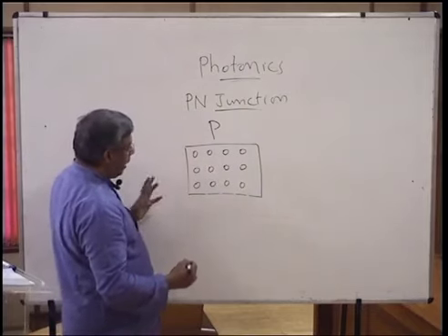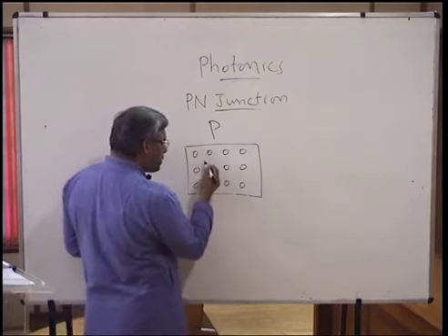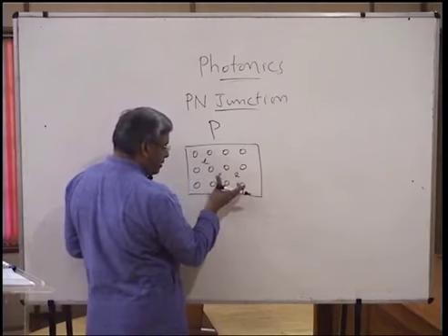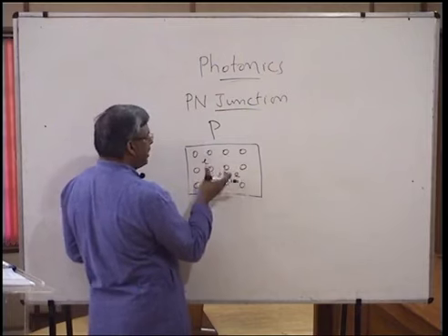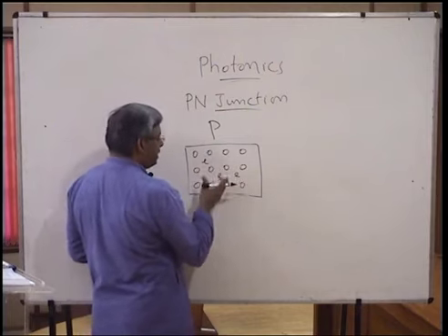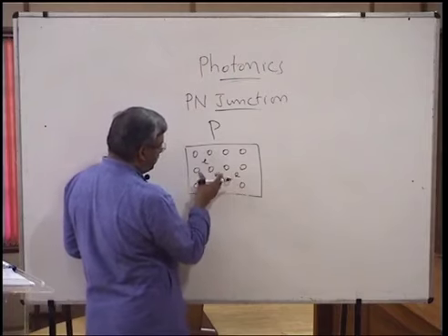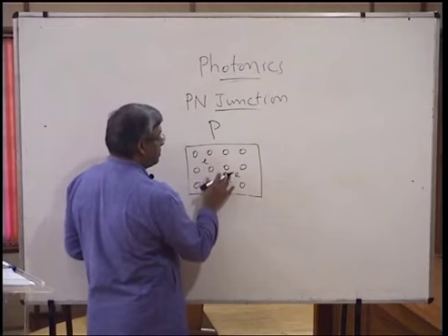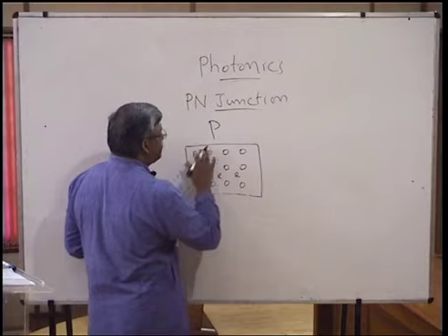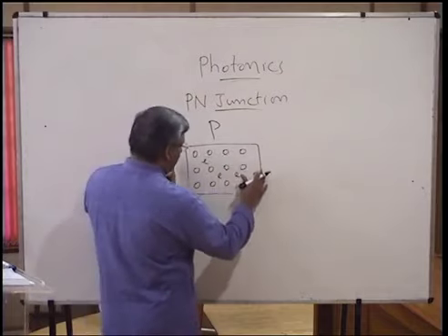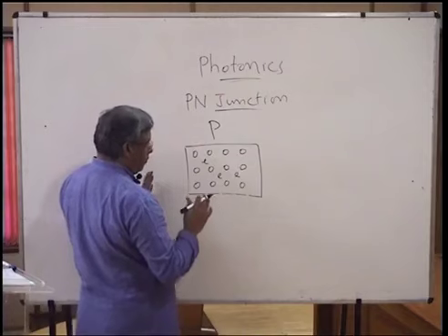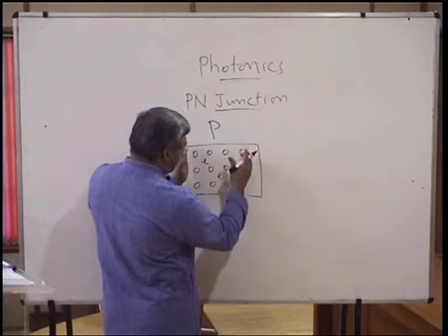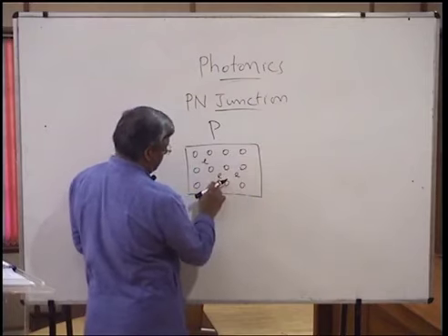So there will be positively charged holes in this particular material when an intrinsic material is doped by a trivalent material. And as I've already told you, there will also be some amount of electrons here, because the intrinsic excitation, thermionic excitation or photo excitation, will give rise to holes and electrons already. So some amount of electrons will be there as minority. The majority will be holes. Therefore we have a definition of a p material: a material with majority carriers as holes and minority carriers as electrons.